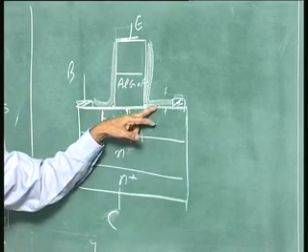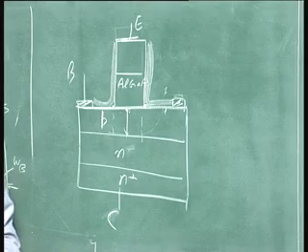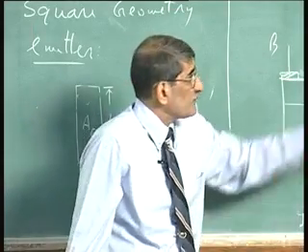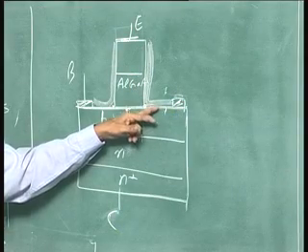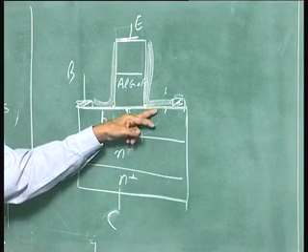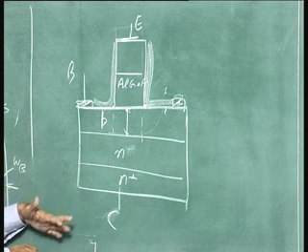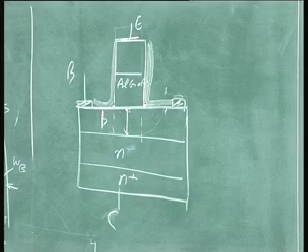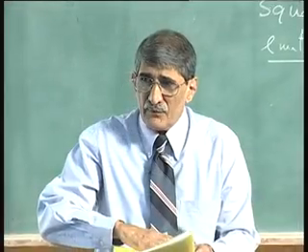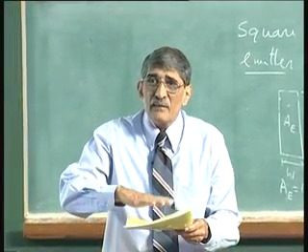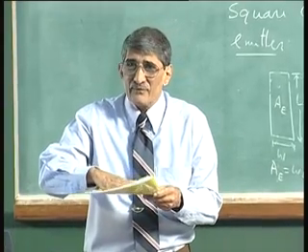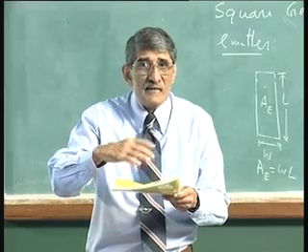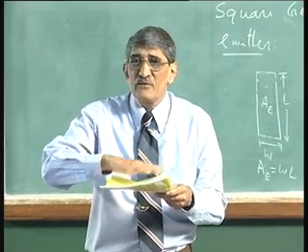But then you say put nitride. These are the steps taken by people: instead of oxide, put nitride. When you put nitride, what happens? You do not get good passivation, because if you have a surface and you want to satisfy those dangling bonds, the deposited layer must be in intimate contact with the surface. It should interact with the dangling bonds. Some sort of chemical reaction should take place for the surface to get passivated.